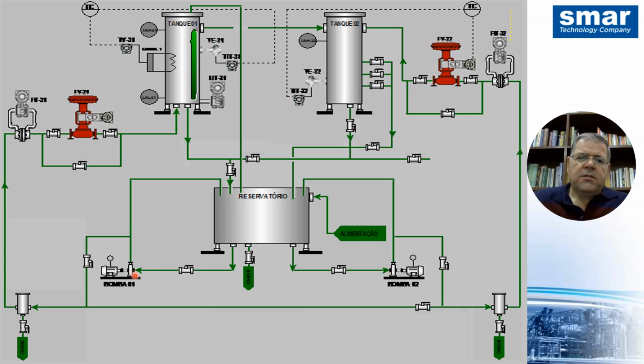Connecting the pump, we direct water into the left side circuit, going through a flow meter with an integral orifice, and then through the valve. This valve has a bypass if manual mode is needed, and goes to a heating tank. This heating tank has two heating elements, which will serve to heat the tank. Additionally, there is a temperature gauge, and we have a level meter besides the flow meter we mentioned here.